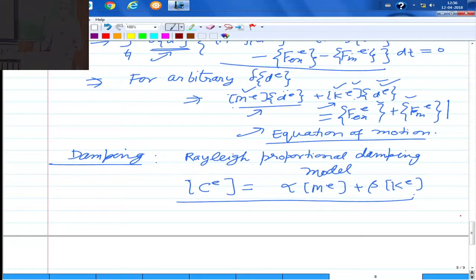Of course, if there is some mechanism present in the system, that can be modeled through the virtual work of non-conservative forces. Damping forces are going to be non-conservative forces because they are velocity dependent in general. They can of course be of other types as well. So you will include them through the W_NC, and you can bring in those contributions to damping. But most of the time there is no explicit mechanism present for introducing damping.